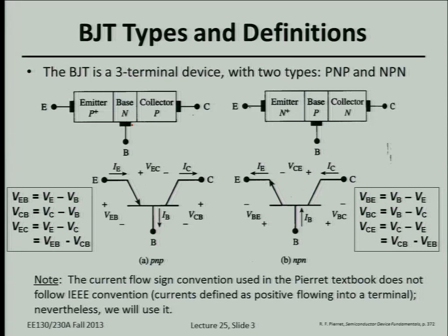Okay, so one thing to notice here in a BJT structure is that it is not symmetric. So that's different than a MOSFET. So in a MOSFET, the source and drain regions generally in an integrated circuit look the same, right? You can't tell which heavily doped junction is the source or the drain until you see what voltages are applied to the MOSFET. But in a BJT, it's actually quite asymmetrically doped. The emitter is usually much more heavily doped than the collector. And by the end of this lecture, you'll qualitatively understand why.